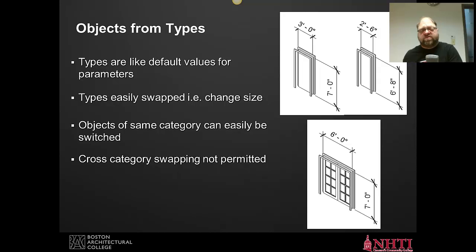It wants me to put a brick wall or whatever kind of wall in, and I don't know that. It's not a problem. You can put something with as much information as you know at the time. So I know that it's going to be block. But maybe I don't know the exact finishes. So I might just place an 8-inch generic wall and later come back and swap that out for something more specific. So this idea of swapping is kind of fundamental to the way you want to work with Revit.